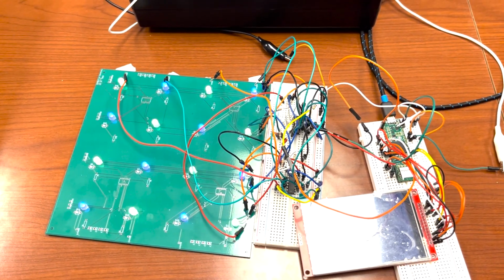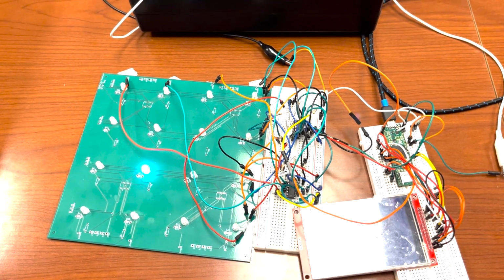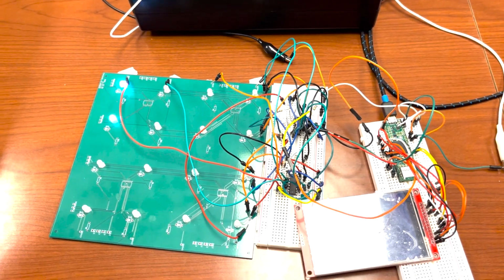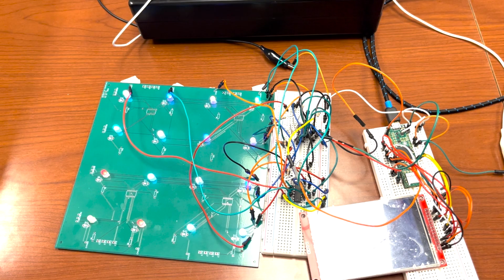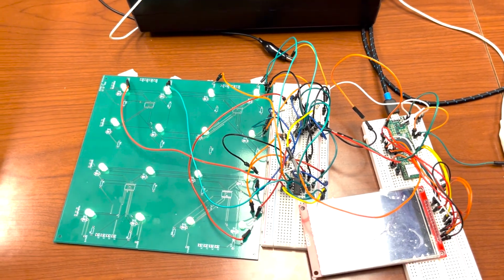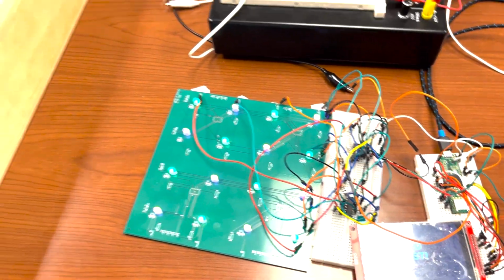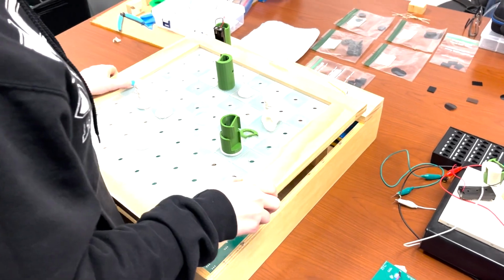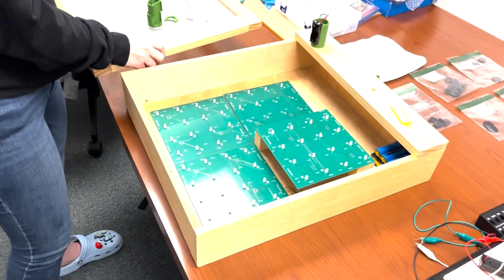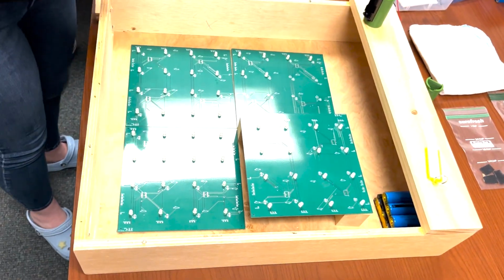And then for the rows, we're using active low, so they will read high, otherwise the row we want to send a signal to will be turned to low in order to turn that row on. Then under here is the full 4x4 of the LED array, just to give you a picture.